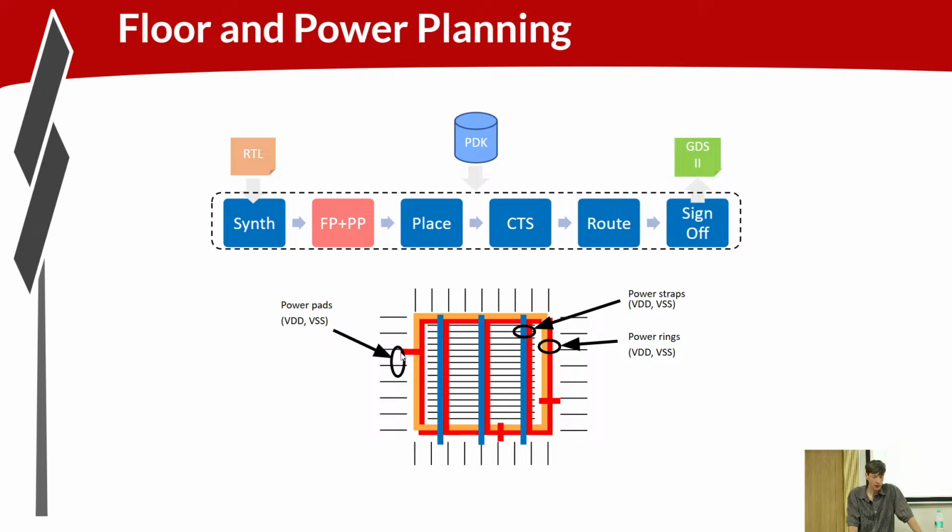So how is power being delivered to the silicon, and how are we distributing that power throughout the silicon? So power and ground, right? VDD and VSS. We will see this when we looked at the 3D flyover view of the ASIC, right? We saw the high-level metals, the big rails on top of the chip. Those were the power lines.